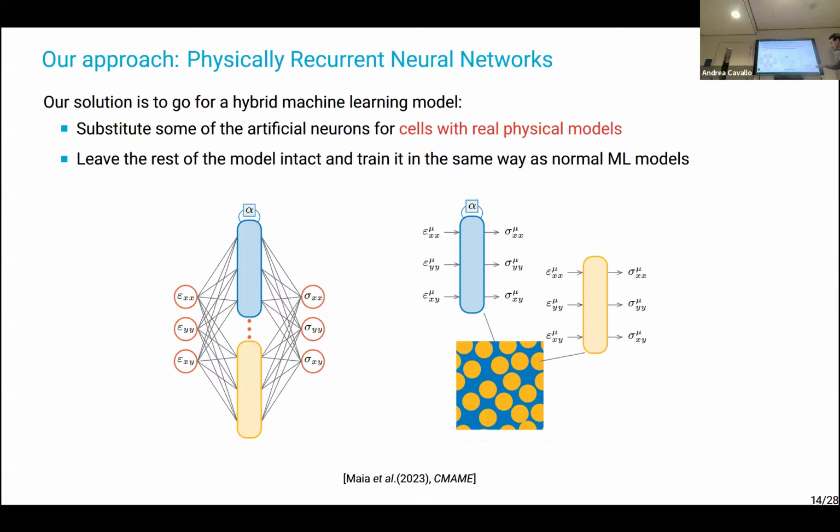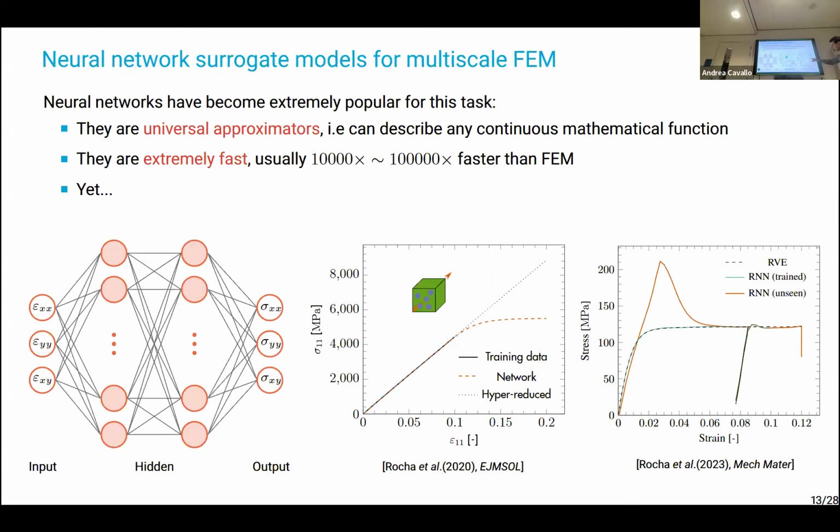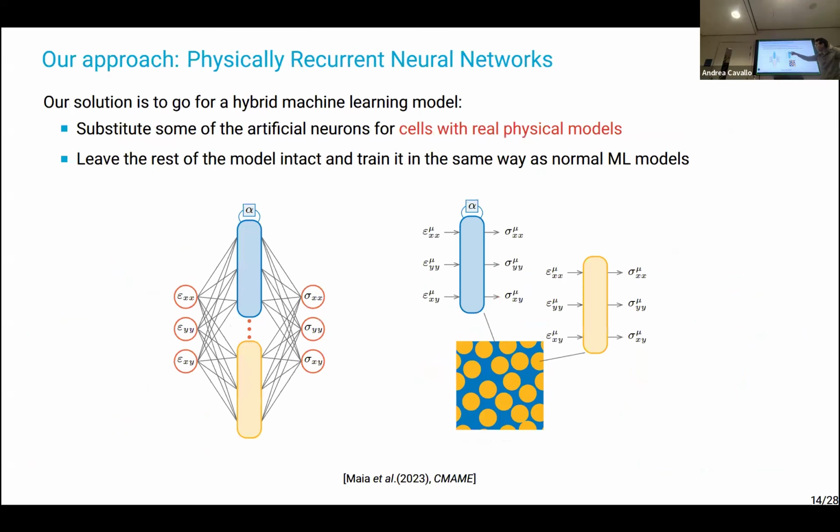So in this case here, the material loads and unloads to a different strain. This would be alpha, how much permanent strain there is in the material. These models know this, and they keep track of their own variables. So this would be the memory of the recurrent neural network in this case, but it's a latent memory that we understand. It's also interpretable then.